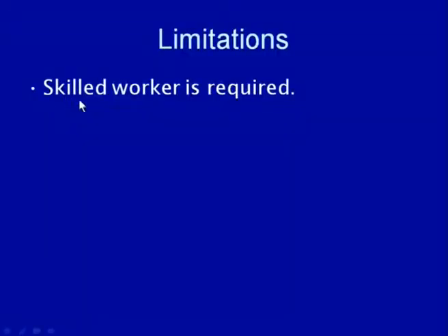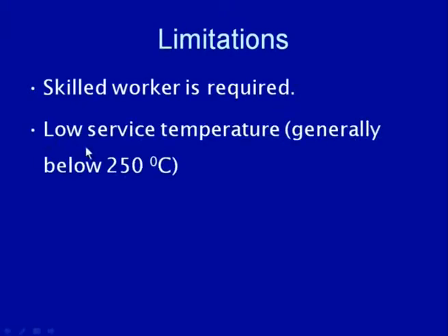But there are certain limitations also associated with braze welding. These are mainly related to the fact that a skilled worker is required for development of the braze weld joint, and further, low service temperature conditions are good enough, but it cannot perform at high temperature.